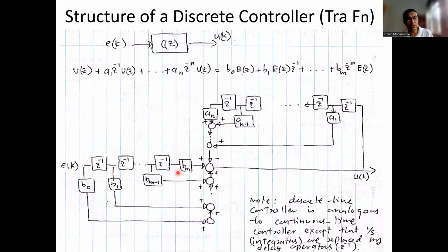If it is a 5-step thing and operating every 1 second, you need to have the error stored in the register 5 seconds ago, 4 seconds ago, 3 seconds ago, 2 seconds ago, 1 second ago, and now. All these errors should be stored in the microprocessor memory registers.